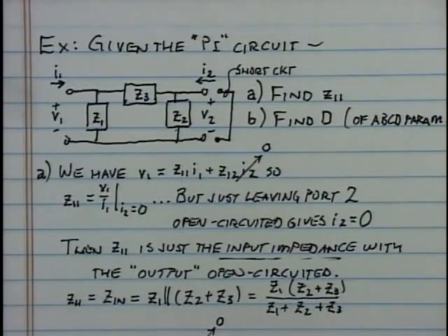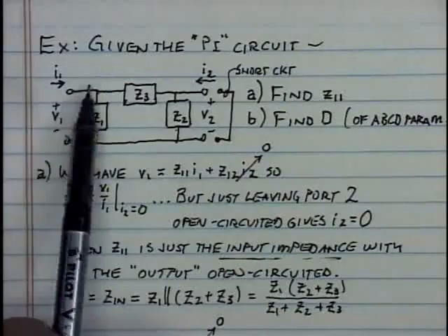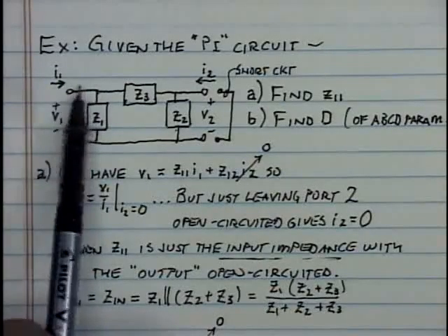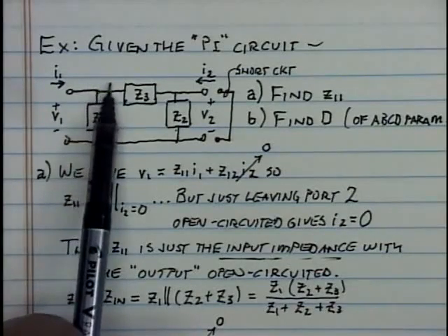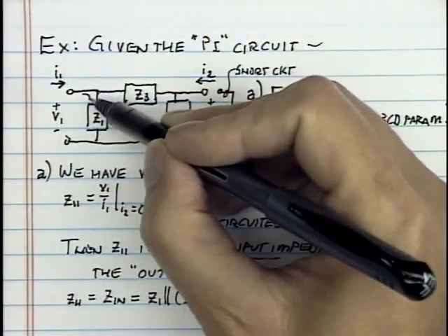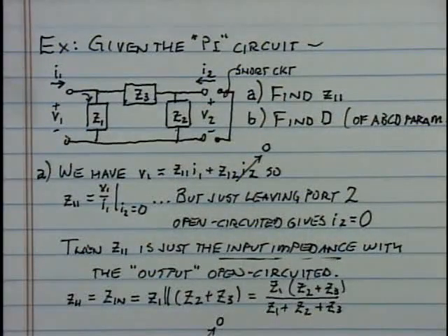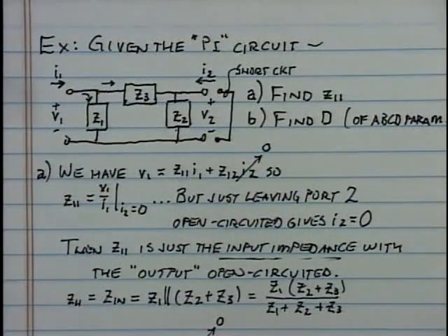So you could effectively take the impedance Z2 right out of that circuit altogether. Ignore Z2, it has no effect. Okay, well, here's the current I1. What happens to that current I1 when it enters terminal 1? It divides I1 partially, flows down here through Z1, and the other part of I1 flows there through Z3.